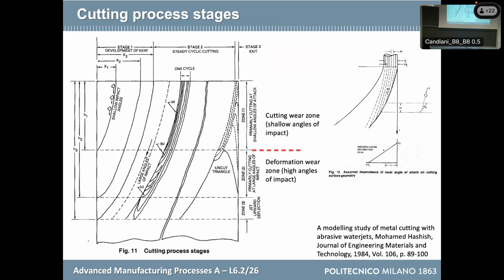But I can add something more, because everything we have said is happening in every cutting curve. The difference will be that some materials will be better cut, for example, at the top of a cutting curve, and some other materials at the bottom. But let me clarify. So these are typical striations that are created by the jet.